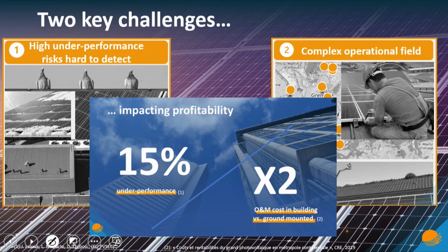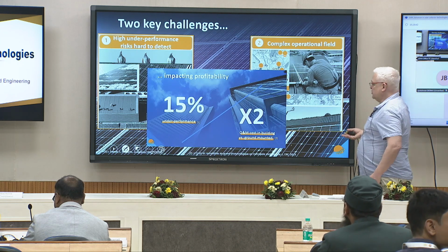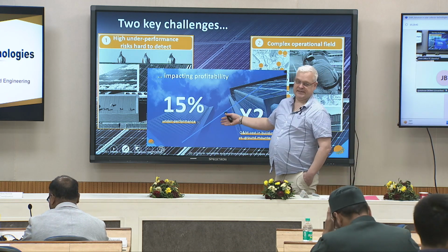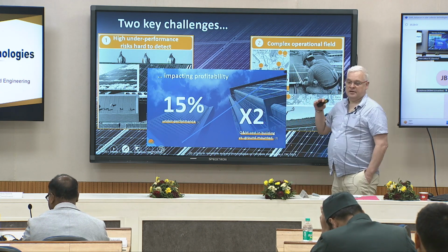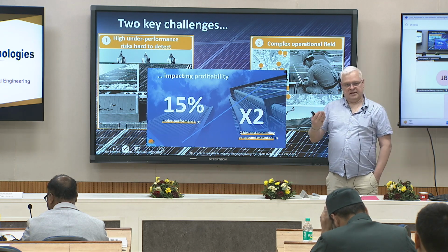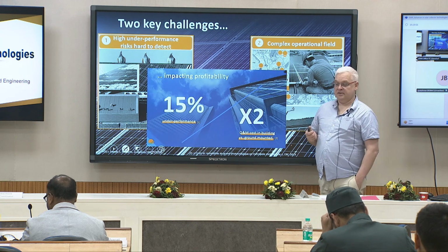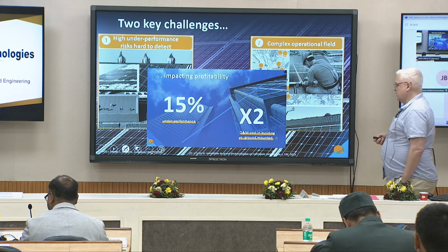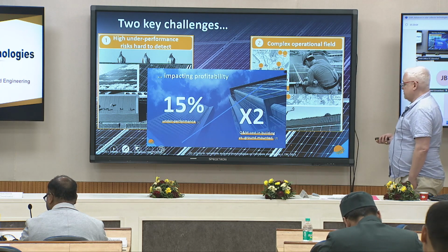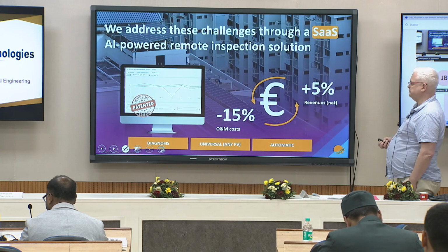You have the birds, of course, that create some dust, even if it is local. You have a problem because you have a shadow point on your cell. So usually we find that in cities, the real performance compared to what is expected is under what is expected, by around 15%. So it's important to identify the reason why.